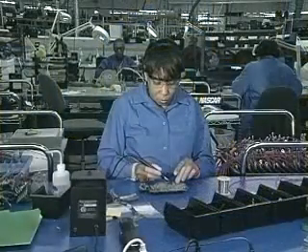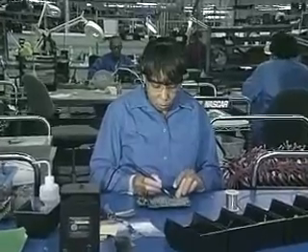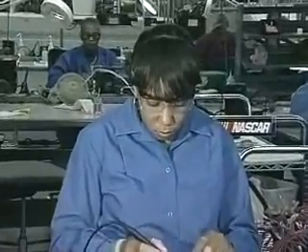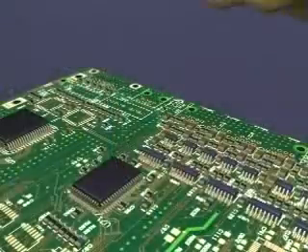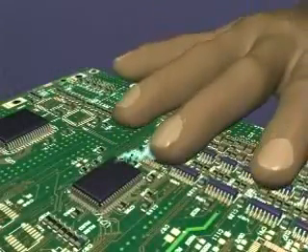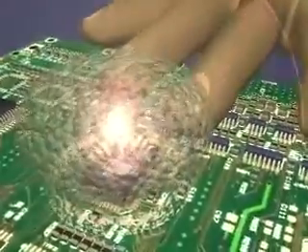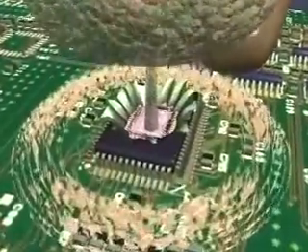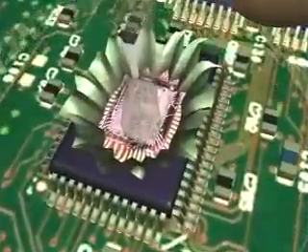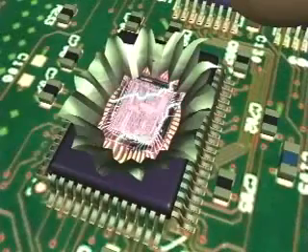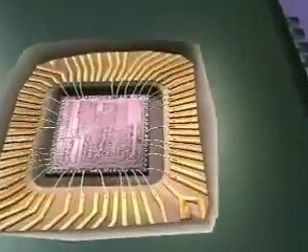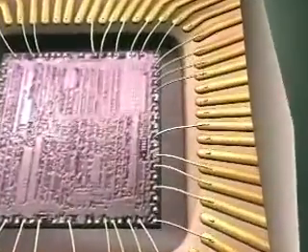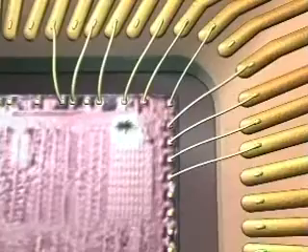People are the biggest cause of ESD. That's because our bodies easily pick up static electricity. In fact, our skin can store relatively large amounts of this electric charge. Doorknobs probably don't mind the spark, but when ESD passes through an electronic device, such as an integrated circuit, it can cause serious internal damage to that component, resulting in a scrapped component. The tiny circuit paths in these sensitive devices can be burned up or severed by an ESD voltage, so small that our sense of touch can't even detect it.